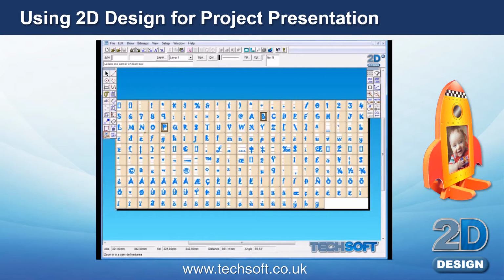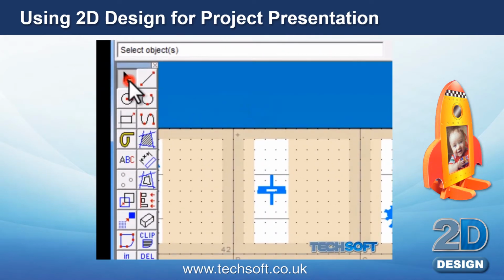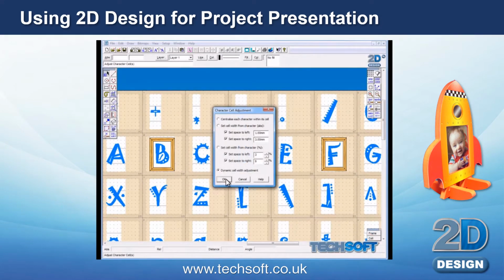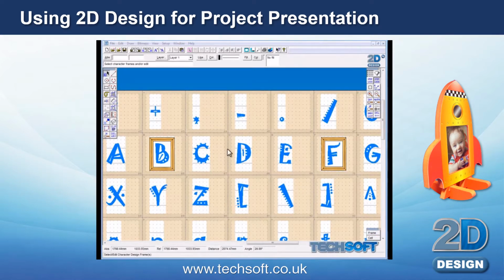Zoom in so that you can see both capital letters B and F. Letters have all been coloured blue and a frame with a textured fill of wood has been added to the B. Select the frame behind the letter B and copy and move it to the capital F. You'll need to send the frame back and then select the F and move it centrally in the frame. Lastly, we need to edit the character design frame to accommodate this wider F character. Choose the select arrow and then cell, click OK, choose the handle and widen the character cell. Choose the font save button and save the font as photo frame.